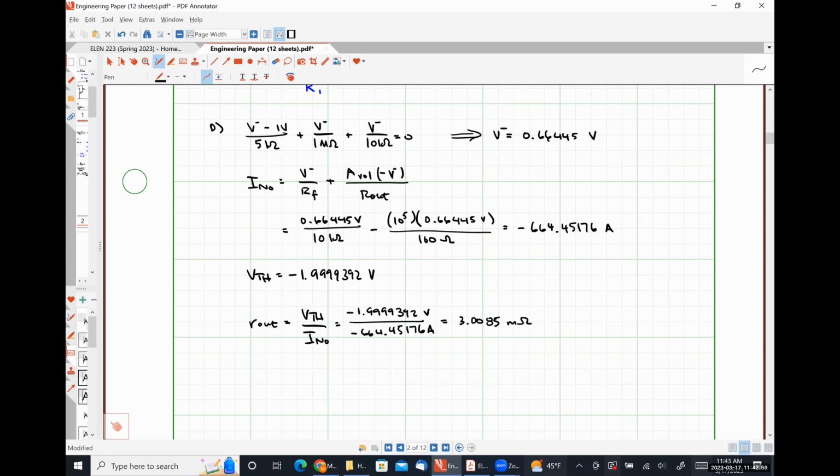Even if our input resistance is only hundreds, 10,000 ohms or something like that, instead of millions of ohms or more. Even if our output resistance is hundreds, if not thousands of ohms, instead of really close to zero, like we would expect for an ideal case. We have to really screw things up in a negative feedback configuration to not have it behave like an ideal op amp, plus or minus 10%.